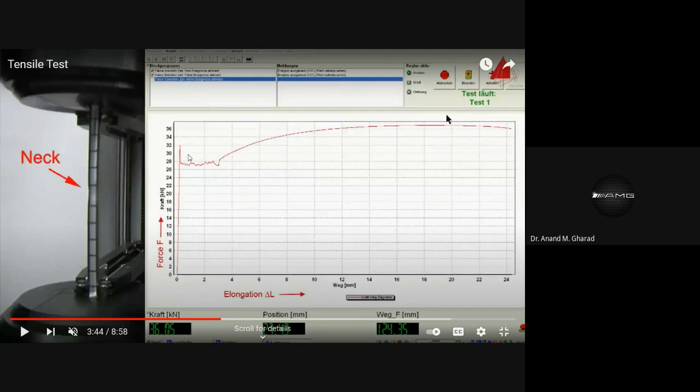In contrast, the working stress method uses only up to this elastic limit. In it too, we apply a factor of safety, and after applying the factor of safety, the value comes out to be somewhere here. Don't you feel so? Isn't it? So the biggest disadvantage of the working stress method is that it doesn't allow us to make full utilization of the material up to its maximum capacity before breaking.